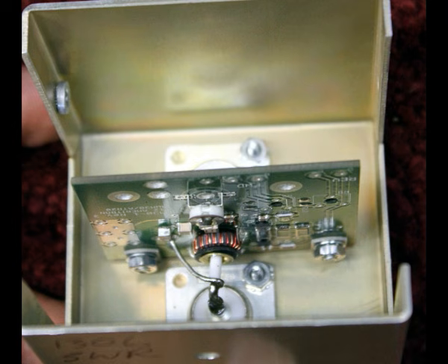Somebody can easily prove that this thing isn't directly measuring the standing wave ratio, because all you have to do is take this bridge when it's set up for a null on 50 ohms and put it in a 75 ohm line and move it along in that line.